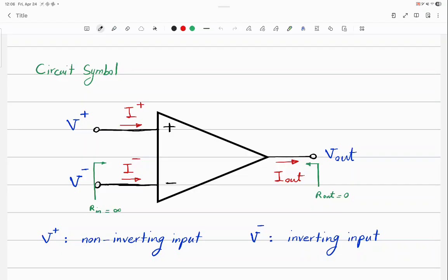Now, next thing is that if you remember the concept of equivalent resistance, for example, we separated 2 nodes or 2 terminals on your circuit, and I ask you to find the equivalent resistance from those 2 terminals, right? Now, if those 2 terminals are the input of your circuit, instead of calling it equivalent resistance or Thevenin resistance, we usually call it input resistance, for obvious reason.